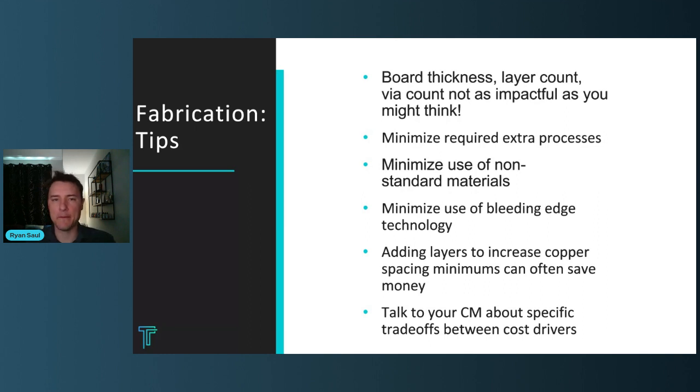It's an adder, but it's relatively minimal compared to a lot of the design contortions that you can get yourselves into trying to minimize these elements. So I would say, don't try too hard to reduce your layer count or to reduce your via count.